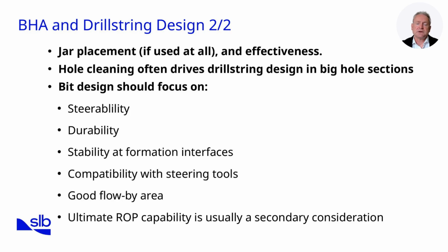In this continuation of BHA and drill string design, we consider additional key points. Jar placement must be carefully evaluated, and in some ERD wells, jars may not be used at all due to limited effectiveness at extreme reach. Hole cleaning often drives not only BHA configuration, but also drill string design in larger hole sections. Components must provide sufficient flow by area to prevent cuttings build-up.